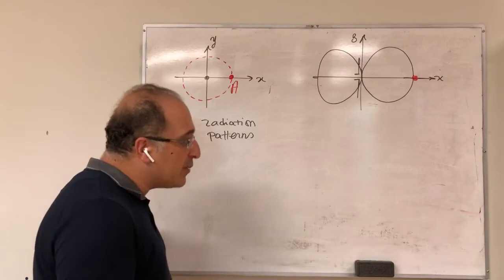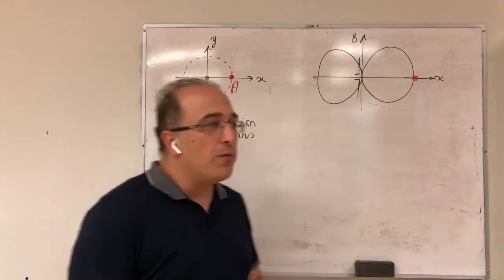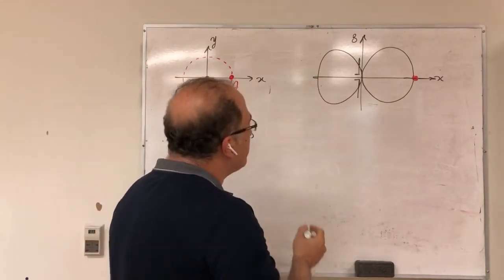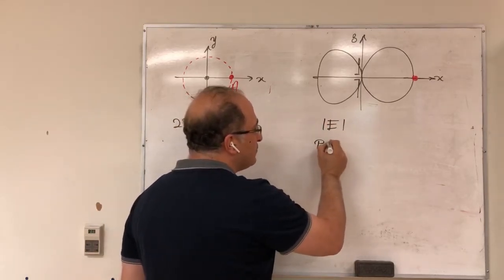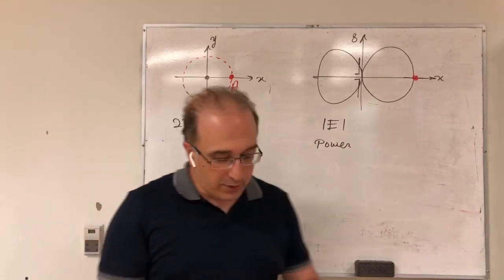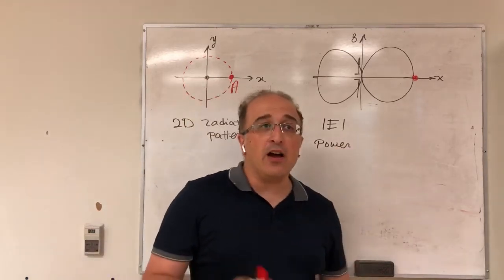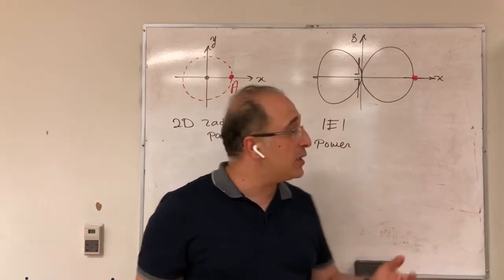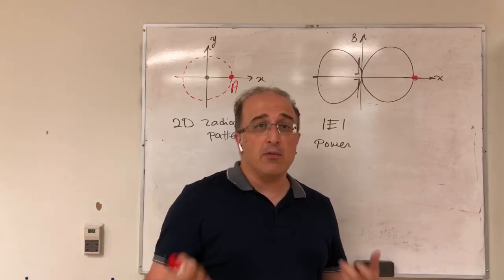So the other thing about the radiation pattern is what in fact we are plotting. So usually in these plots that I have, I either plot magnitude of electric field or power. So it's either magnitude of electric field or power. For example, your measurements are either field measurements, which is the electric field measurements often, or they're measuring the power received by receiving antenna.